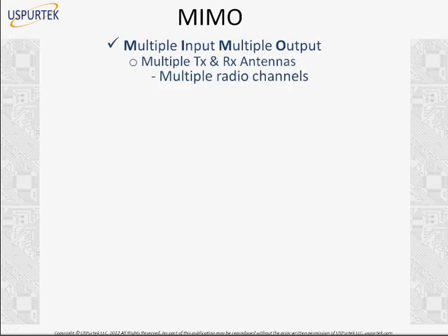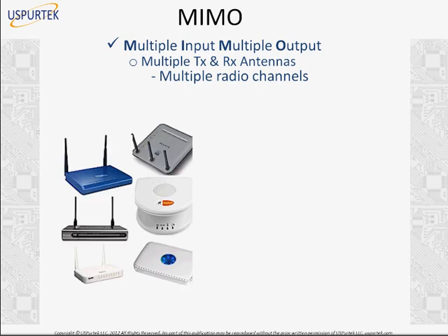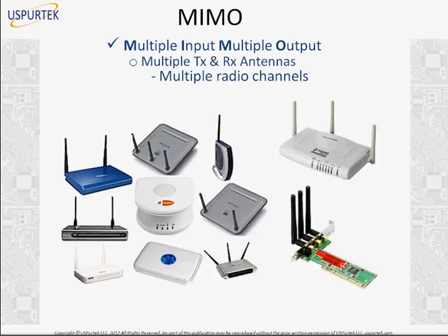Okay, with that said, let's start with MIMO, multiple input and multiple output. Most of you must have heard this buzzword in the 4G wireless telecom industry, but let's see what it is. Basically, in MIMO you have multiple transmit as well as receive antennas. In previous webinars, we have seen that you can have a phased antenna array on the transmitter, on the base station, you could have multiple antennas, because it's very easy to install antennas on the transmit side or the base station side.